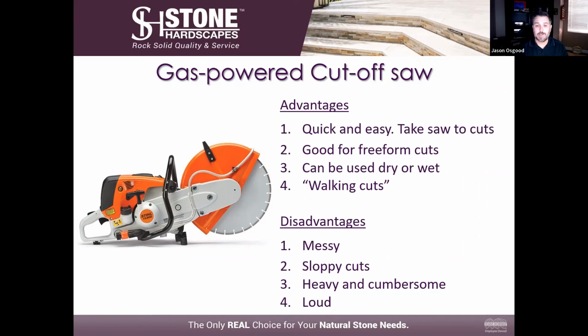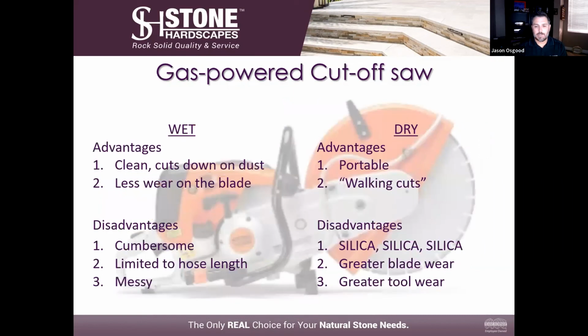Now, it also has some tremendous disadvantages. It's messy. The cuts are sloppy. The tool itself is very heavy and cumbersome, specifically when it's running and the centrifugal force of the blade. If you're not prepared for it, it will wear you out, and it's loud. But as I said, it is by far the most popular cutting tool in our industry.